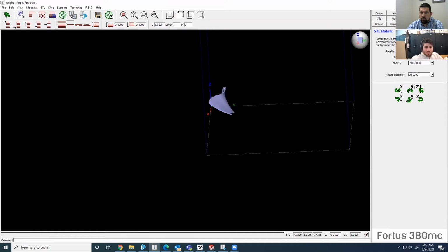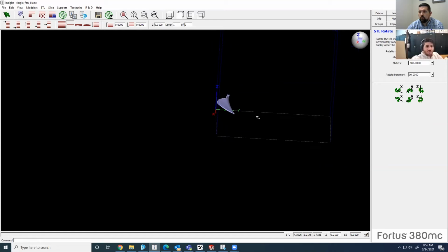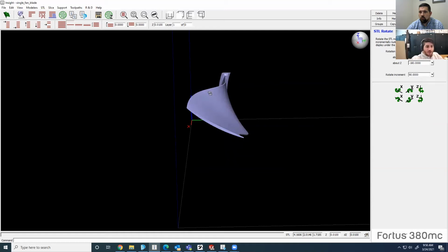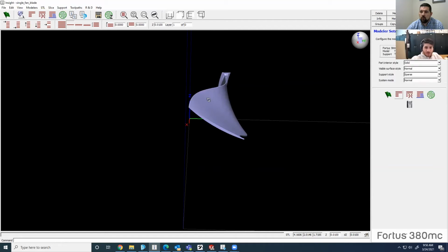And if I want to be a little bit more sure, this part should be just fine, but if it didn't curve quite as much over here and it was a little bit more straight, I would feel a little less secure about printing this part. I'd be worried about the machine going back and forth like this to fill in the raster, causing the part to wiggle a little bit, and you would notice that in the part. So what we can do is slice the part,